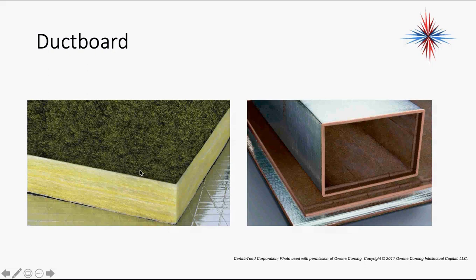Okay, so again, just be aware that there's ductboard out there. Oh, by the way, never step on this if this is in an attic. It cannot support your weight. Okay, be careful working around the stuff because it will break down, and if you step on it, you own it.